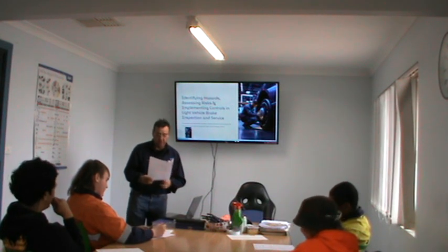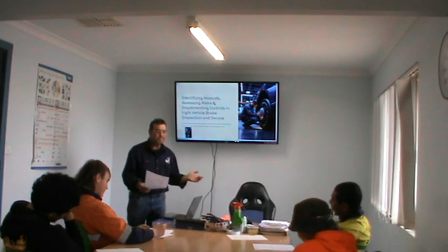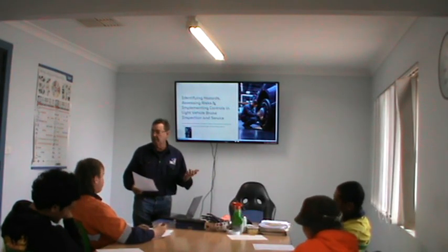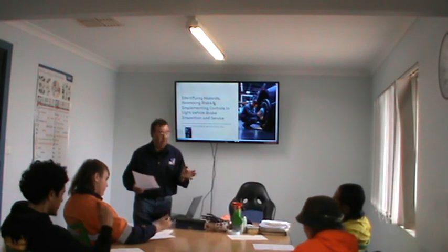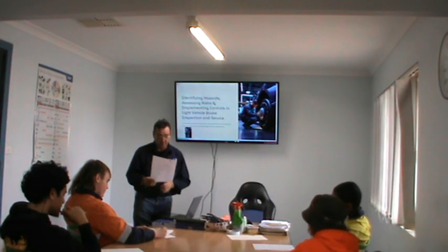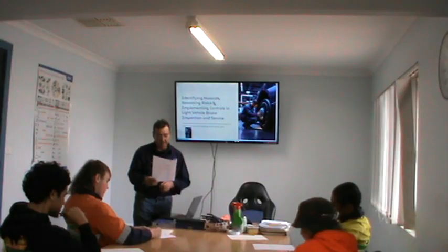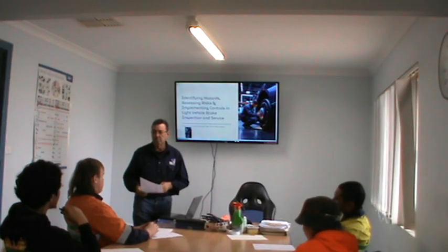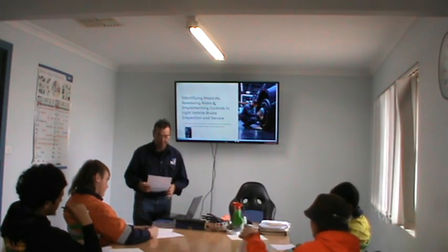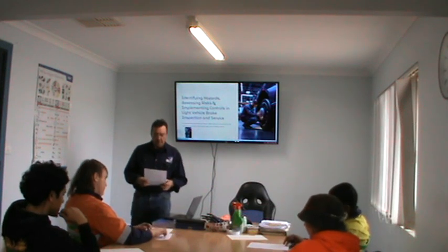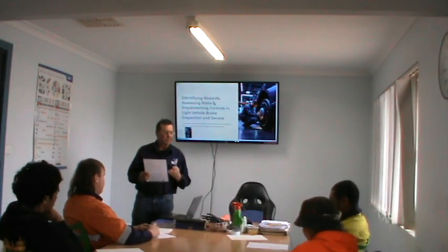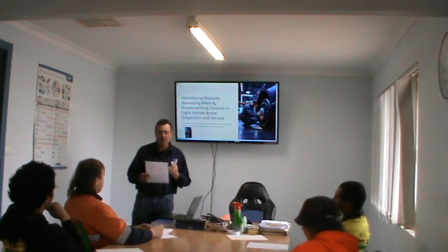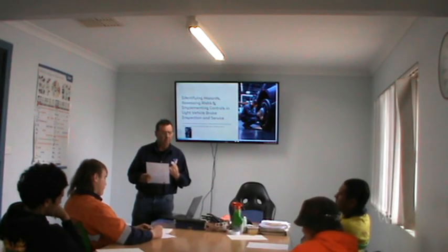Which situation could lead to a slip hazard in a workshop? Brake fluid leaks on the floor, spilling it on the floor. Yep. Leaving your tools lying around all over the place probably causes you a slip hazard as well, but we're talking about brake fluid here. Wearing gloves can help reduce the risk of skin exposure to brake fluid. True or false? True. If you are working under a lifted vehicle without proper support stands, what type of hazard are you going to be exposed to? Getting crushed. Yep, crushing.